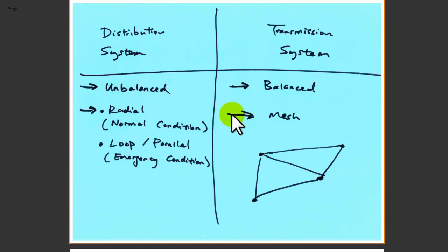Particularly if you learned from 4221 and 4222, those courses teach you how to run a load flow analysis on a per-phase basis, and the construction of the Y matrix is built based on the mesh topology of the network. So handling the inverse of the Y matrix may not be as tricky as the three-phase, more inflated version of the Y.